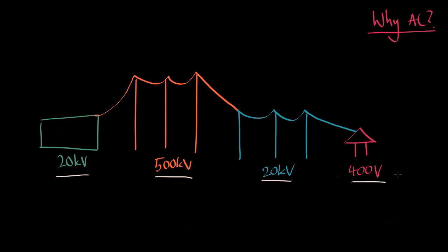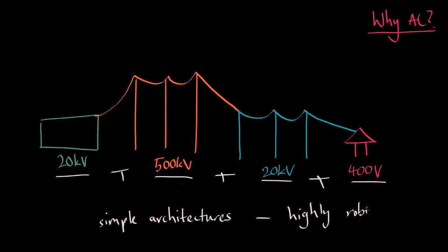These all operate across a range of voltages, meaning that vast amounts of power must be regularly stepped up and down, requiring optimal transformers to minimize power loss. AC transformers are preferable to their DC counterparts as the alternating flux allows for simple architectures that are highly robust and have minimal power loss over expensive and wasteful power switches.